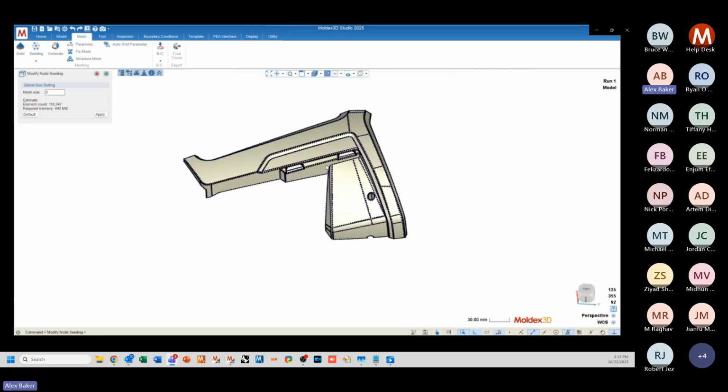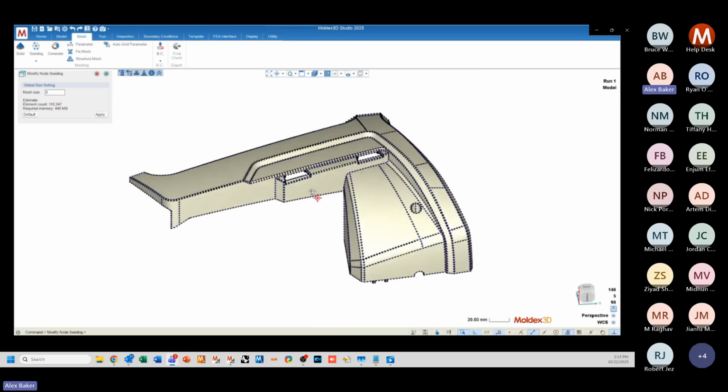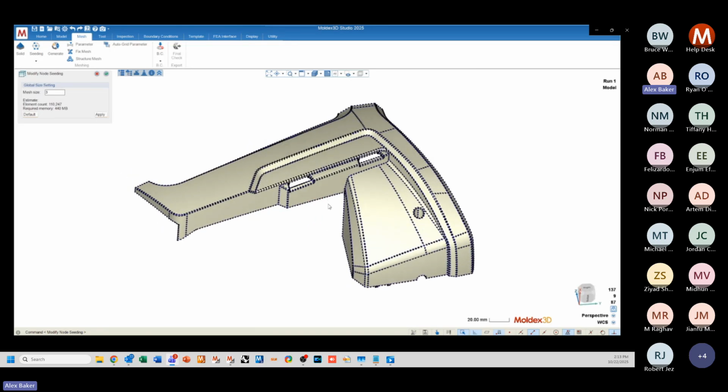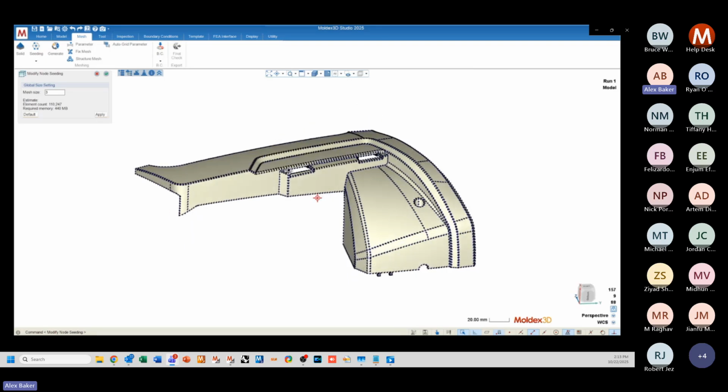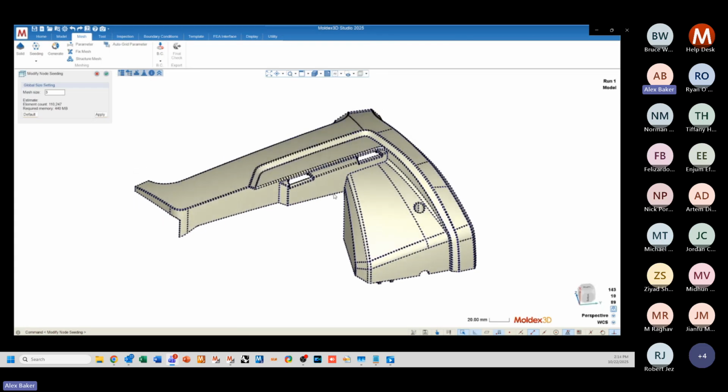What we're going to do is optimize the number of nodes with the number of features across our geometry. And to do that, there's a specific methodology that we call the Goldilocks node seeding. We're going to have to rotate to a very specific viewport, and then we're going to specify our node seeding based on the nominal distance between those nodes.